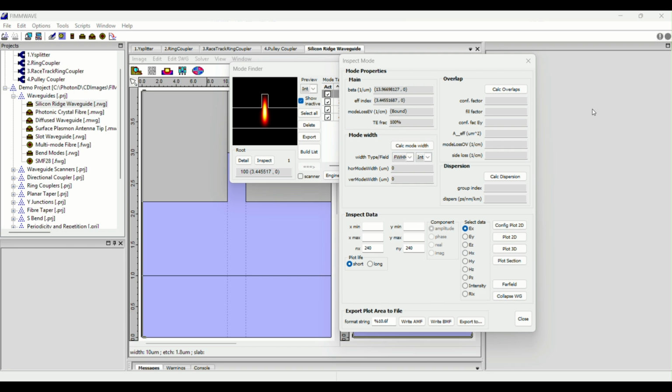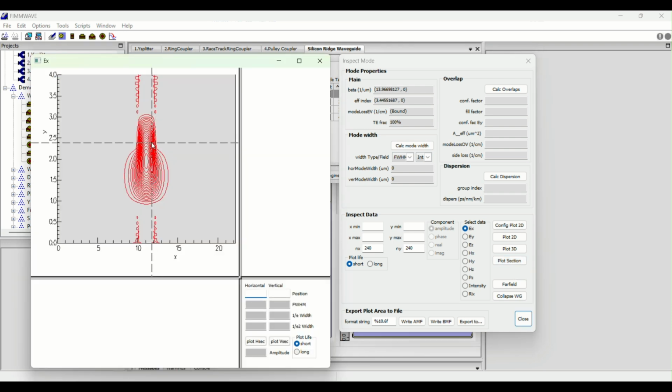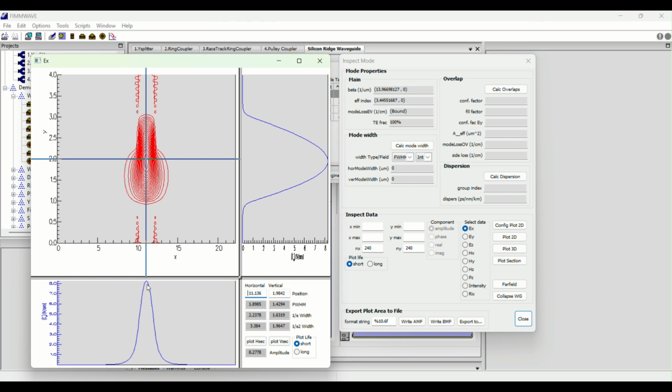During this video, we're going to assume that the cross-section of your waveguide has been correctly optimized. There's another video on this already, but just in summary, you can use the plot section tool. If we just click in the middle, we can see the amplitude of the mode has gone to 0 and its gradient has gone to 0 before reaching the boundary conditions of our cross-section, both the left and right and up and down, the X and the Y.